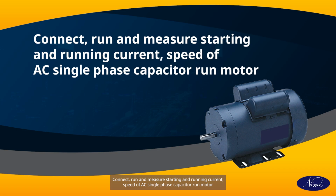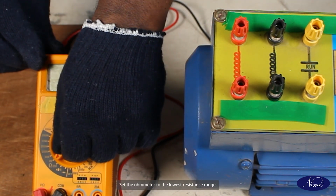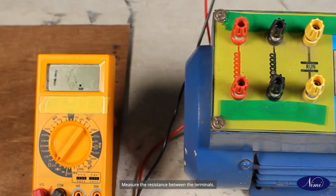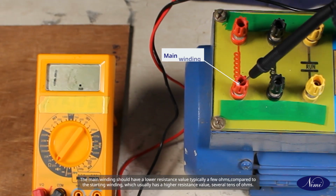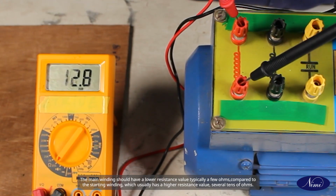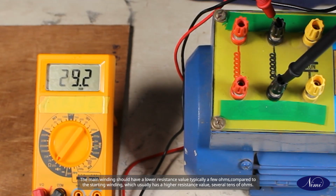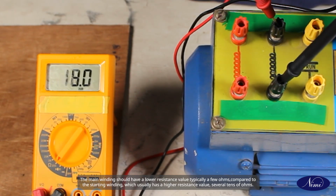Connect, run and measure starting and running current, speed of AC single-phase capacitor run motor. Identify the terminals of starting winding and running winding. Set the ohm meter to the lowest resistance range. Measure the resistance between the terminals. The main winding should have a lower resistance value, typically a few ohms, compared to the starting winding, which usually has a high resistance value, several tens of ohms.